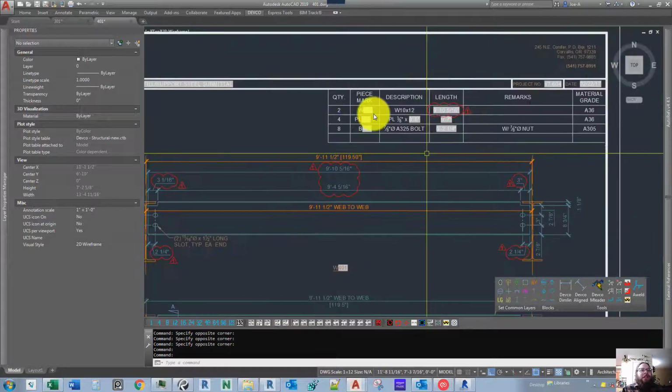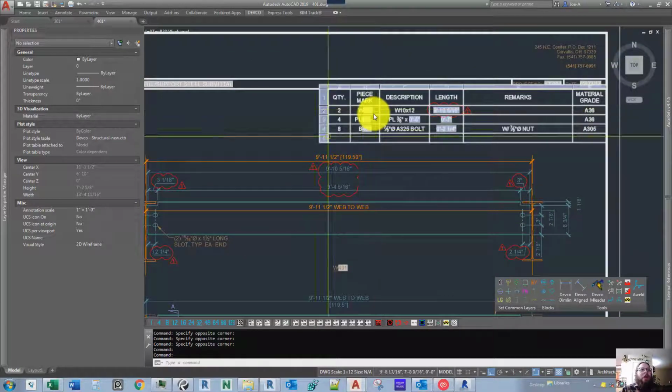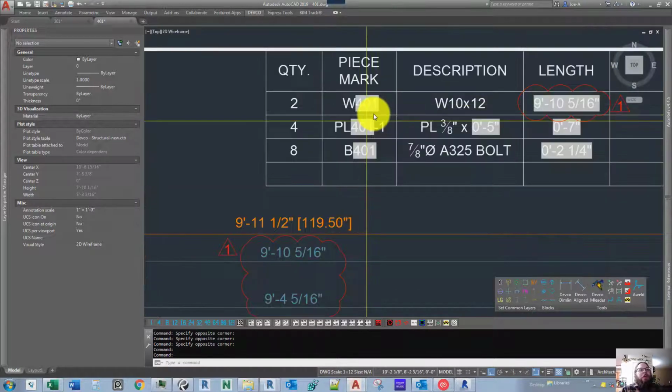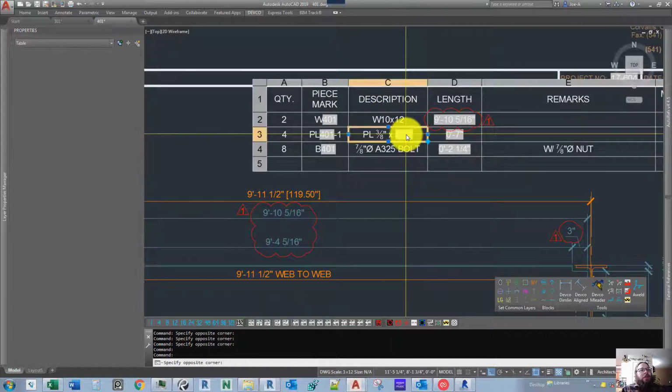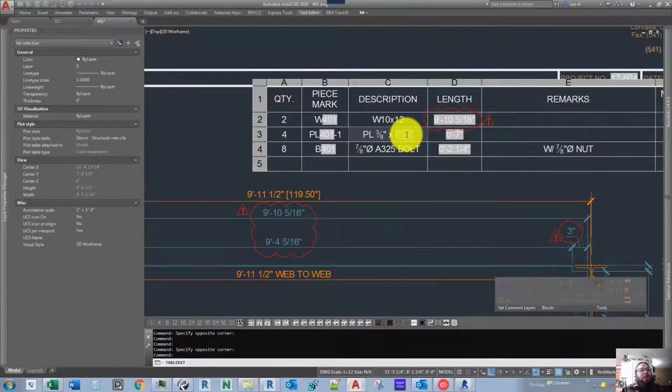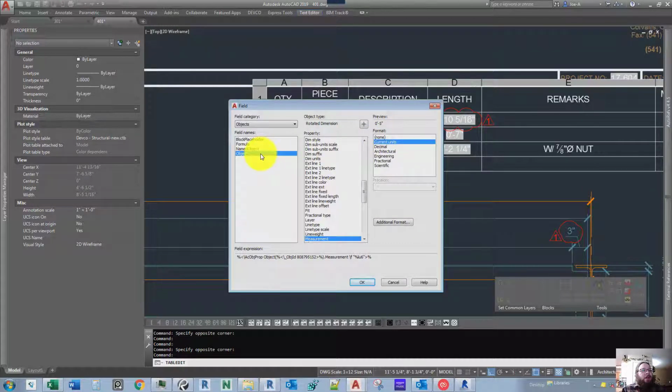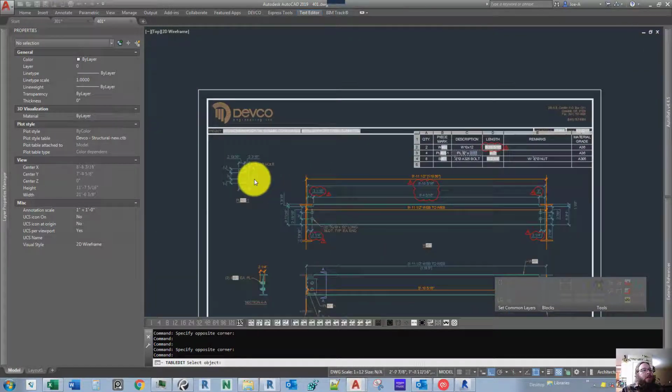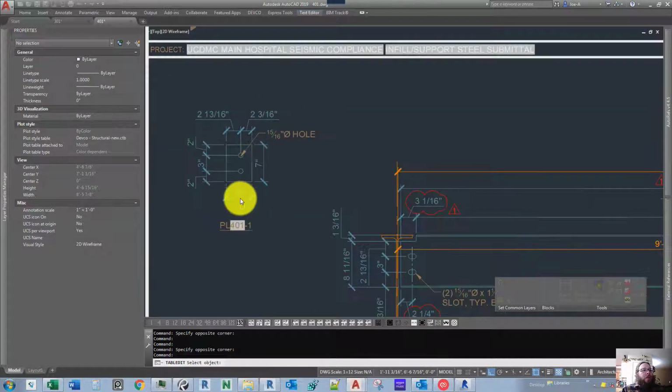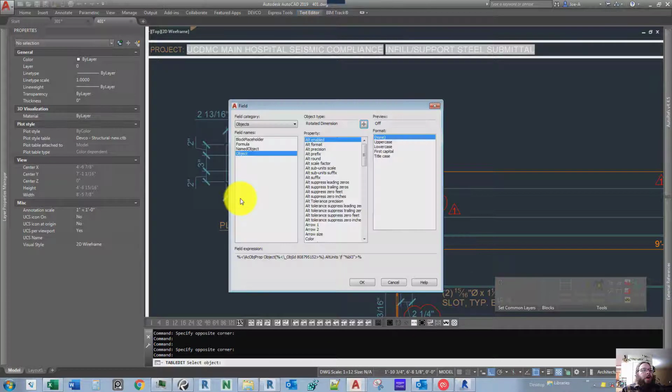And so let's say I saved out this drawing as a new name, all of these would be updated to 402, 403. And you can also use fields for entities too. So here I have this plate. I wanted that dimension to change if I ever had to change it. And so it's set to an object and measurement. See how I've set the object type to rotated dimension? So basically what you do is you pick the dimension you want it to copy, or to monitor basically.